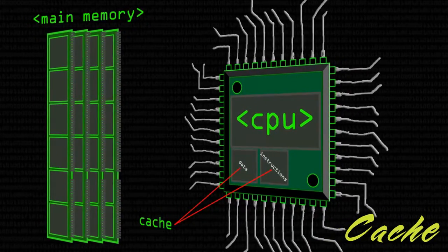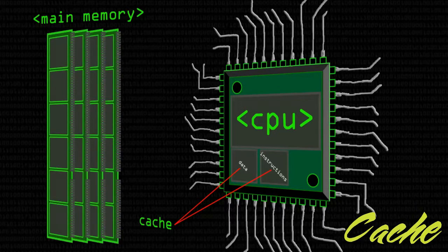So we don't need that much. You often use separate caches for the instructions and for the data so that you don't remove the instruction that you're interested in to put a copy of the data that you're going to process in there.